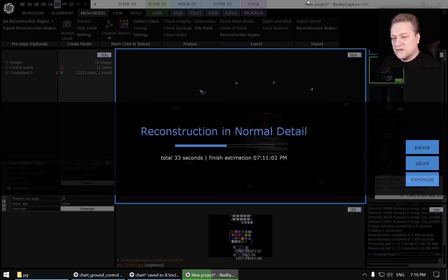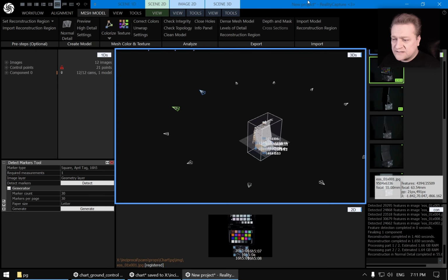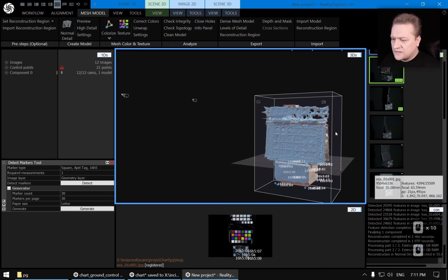We will cover those cases in a special advanced section of the processing, where you can start doing tricks of using one image set for one set of processes and a different set of images for different processes, and that way it's possible even without using structural or laser scans. You can still get much better results out of photogrammetry.